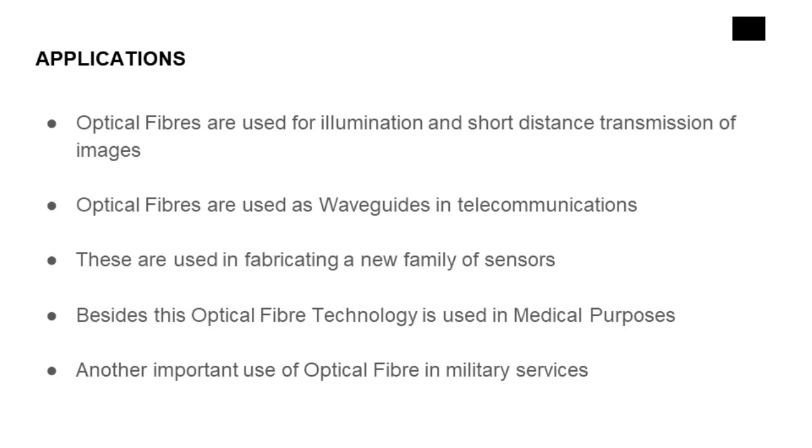The primary function of such bundles is simply to conduct light from one region to another. Such flexible light carriers are relatively easy to make and inexpensive. They are used for illumination purposes. When the fibers are carefully arranged so that their terminations occupy the same relative positions at both bound ends, the bundle is said to be coherent. Such a bundle is capable of transmitting images.